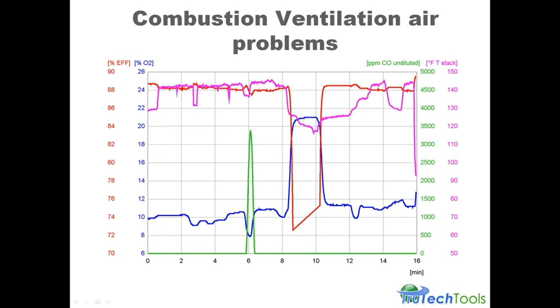But what's happening here is I had an elevator in a building where they had taped off the upper part of the shaft to do some repairs on the elevator. So as the elevator is going up and down in its building, it's acting like a giant plunger. And when it would go up, it would depressurize the basement, suck all the air right out of the combustion air zone of the basement, and the boiler room would go into negative pressure, and the boiler would trip the pressure switch. In this case, again, the contractor adjusted the boiler till the pressure switch would stay in. And then when the elevator would come back down, it repressurized the room. So what we're seeing is the elevator going up and down a couple floors. All of a sudden it went up to the top of the building, and the O2 level dropped to a point where it affected the combustion enough that it actually started to make massive amounts of CO.